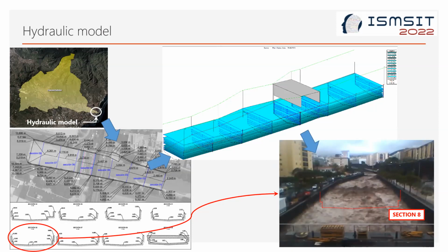For this reason, a hydraulic model has been created by HEC-RAS. This is a computer program developed by the U.S. Army Corps of Engineers to perform one-dimensional and two-dimensional calculation for a complete network of natural and built channels. We can do simulation with this model from the rainfall data for February 2010 and compare them with the real images in order to see which of the theoretical methods used to calculate runoff flow is closest to reality.